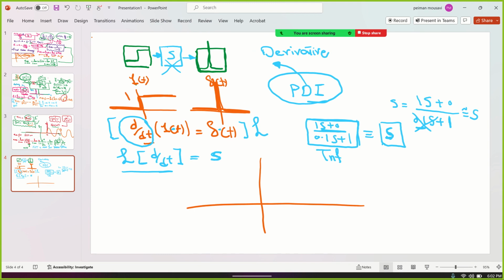If I want to give you a very trivial explanation, let me take you back to high school. This is a graph. When I say derivative, in milliseconds, you're going to find slopes here. How does it look? Lots of noise. That's right. So that's why we want to avoid the single D controller when designing controllers. We always use PD controllers, I'm going to teach you, meaning proportional and derivative together.